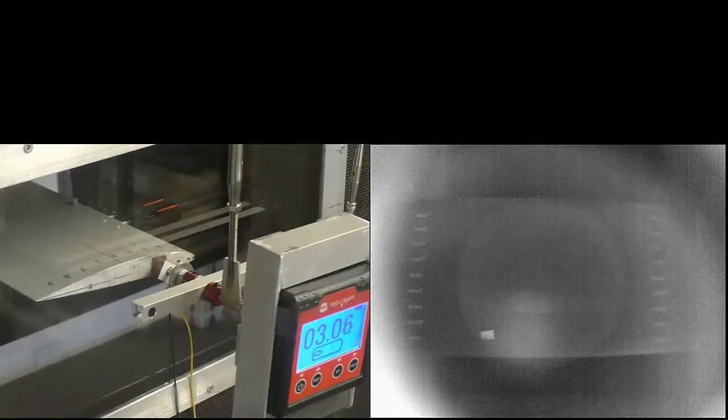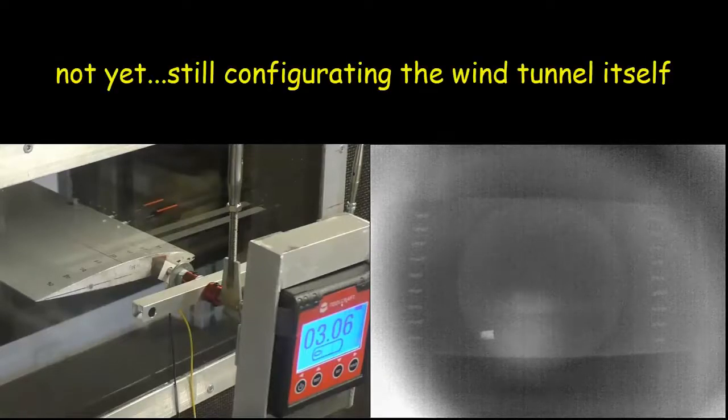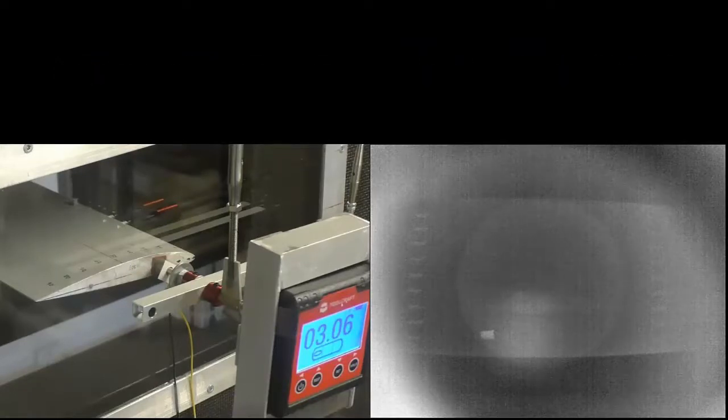The record below shows the profile performing a continuous sweep. However, since the surface is thermodynamically always a little bit inert, it can happen that one does not observe the thermal footprint of the actual flow. Instead, one probably observes the temperature distribution of a previous flow state. The reason is the heat capacity of the material the model is made of.